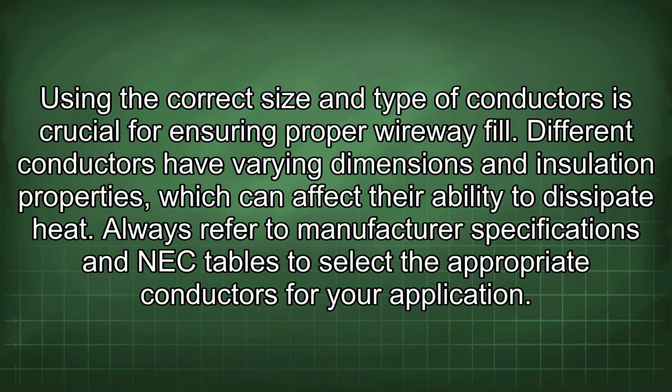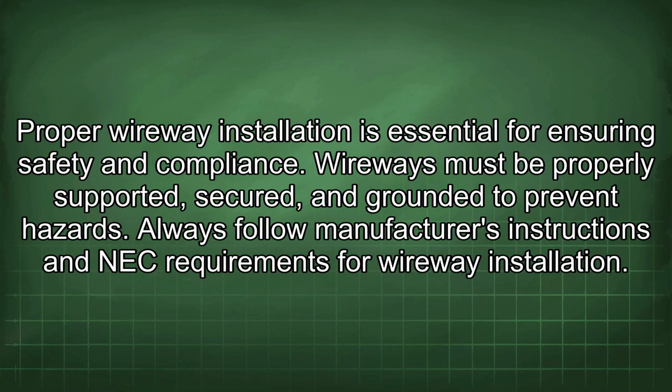Using the correct size and type of conductors is crucial for ensuring proper wireway fill. Different conductors have varying dimensions and insulation properties, which can affect their ability to dissipate heat. Always refer to manufacturer specifications and NEC tables to select the appropriate conductors for your application. Proper wireway installation is essential for ensuring safety and compliance. Wireways must be properly supported, secured, and grounded to prevent hazards. Always follow manufacturer's instructions and NEC requirements for wireway installation.